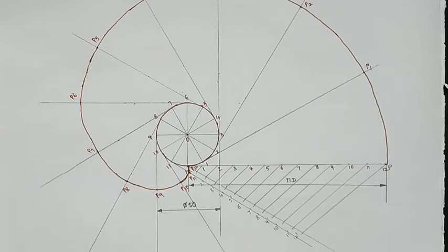Now from the points on the circle we will draw the tangential lines from point O1, O2, O3, O4 up to O12, by making an angle of 90 degrees. After drawing the tangential lines, measure the line length of 1 to P, 1 as center, draw the arc. 2 to P, measure, 2 as center, draw the arc and locate point P2. 3 as center, 3P radii, draw the arc and locate point P3.